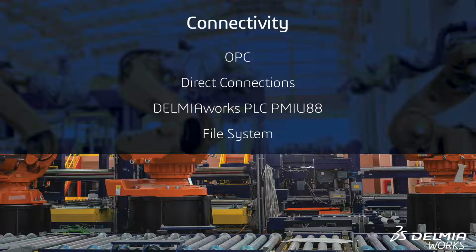Legacy PLC and field components can be made to be OPC compliant when bridged and connected using their legacy drivers and protocols to an OPC server. The OPC server is then a conduit that can communicate data continuously among PLCs on the shop floor and real-time process monitoring. A leading OPC server is KEPServerEX, which DELMIAworks has selected and fully supports.